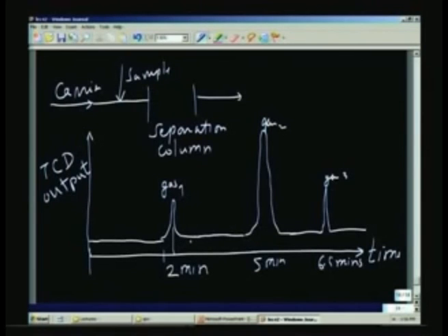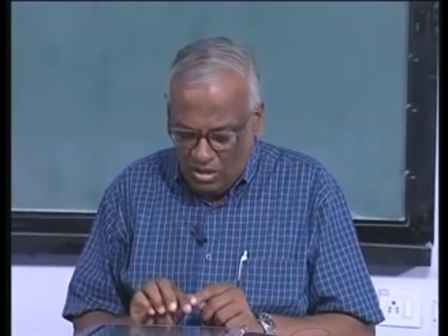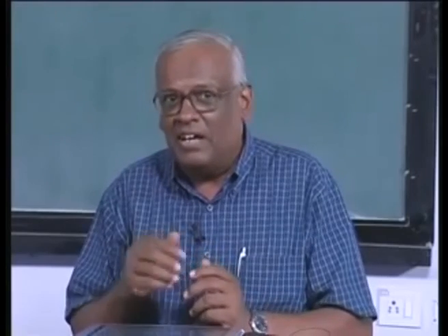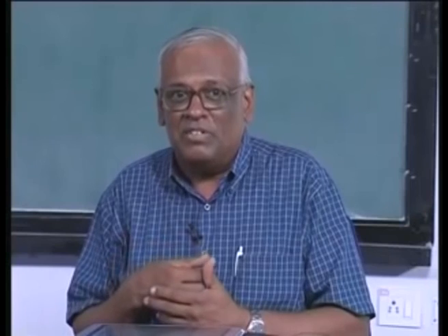and a small concentration is present. Of course, the gas concentration depends also on the thermal conductivity ratio. So, we have to correct for the thermal conductivity of the particular species, or we can do the following. We can calibrate the instrument with different mixtures with different gases and find out what is the output for a particular gas, and accordingly we can find out what is the scale factor for that particular gas and then introduce that in the quantitative interpretation of the signal.